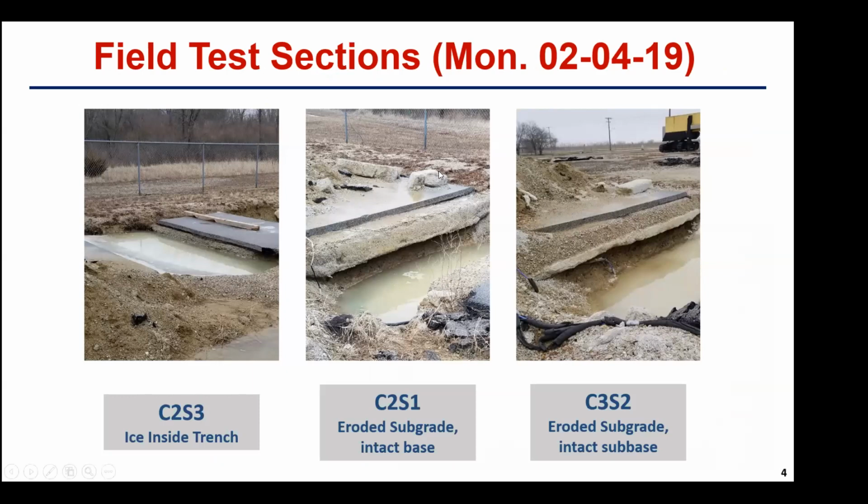So what inspired this project, or how did we get into investigating the durability aspects of this section? Actually, this is part of the reason. This shows the test sections after they were trafficked and trenched to get some depth or height measurements. What we saw after having those test sections open, with trenches open for more than a year, and having those test sections built for more than 3.5 years when these pictures were taken, is that the subgrade underneath many of the sections, as you see in those pictures, had eroded. But then those quarry byproduct sections or subsurface layers were just standing there as cantilever beams on top of the eroded subgrade.